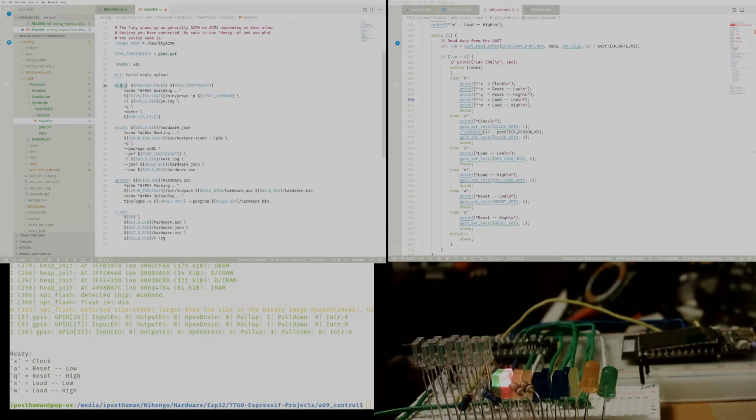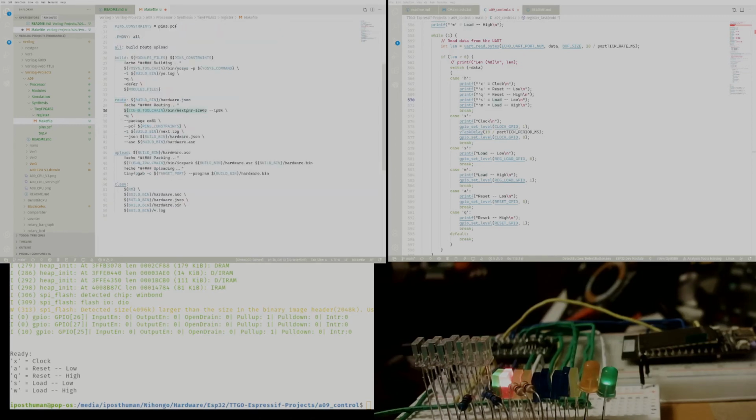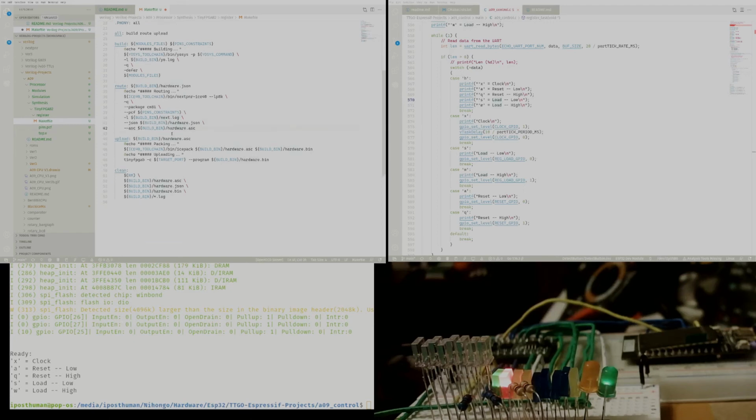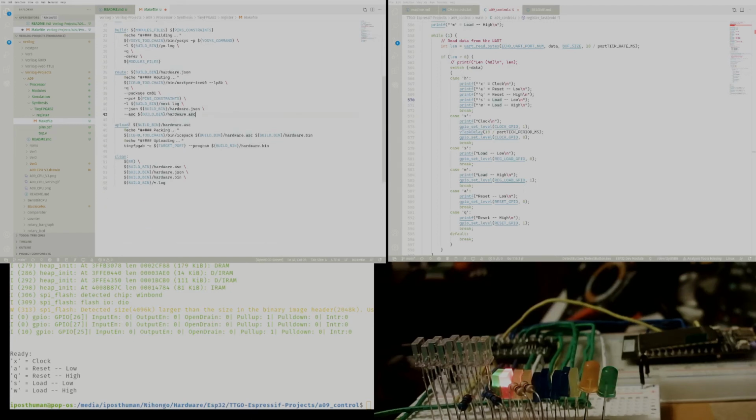So here's our first target. We activate the Yosys command. We pass it the command, some outputs for deferring some warnings and stuff, and then what we're actually going to feed to the builder. We also have the next stage, which is perform routing, and for that we need the nextpnr, the newer version of the place and route tool. We tell it what chipsets we're using, some packaging constraints, outputs for logs, where some input and output files are going to, and then finally we're ready to upload it if, of course, the build and the route succeeded.